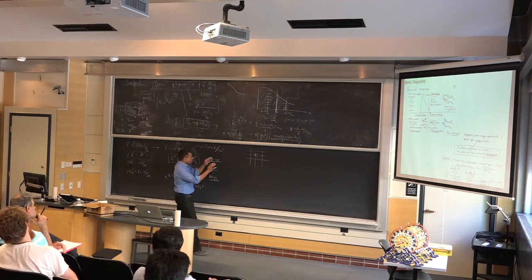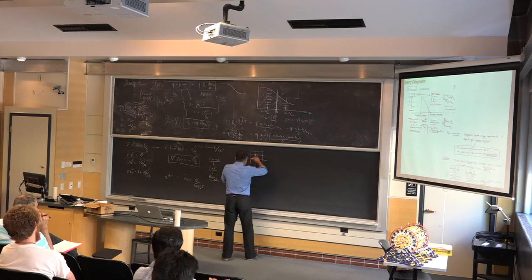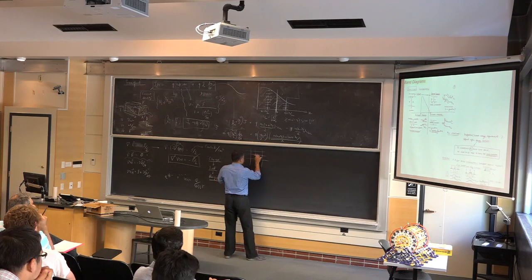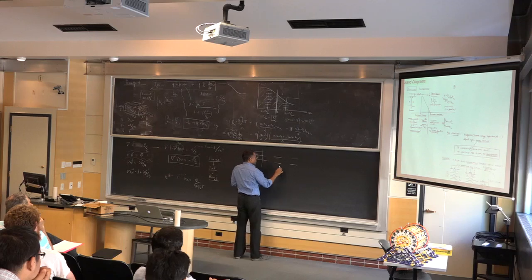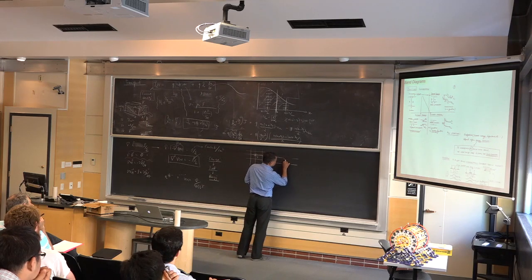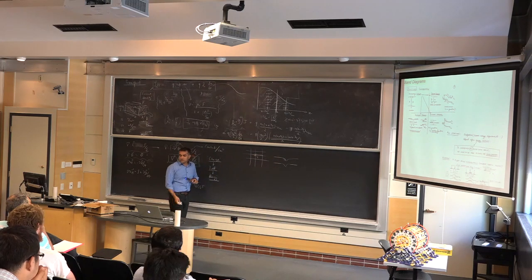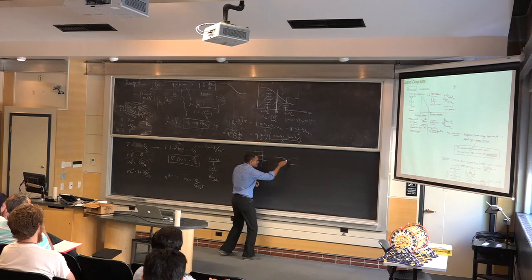If you want to draw the energy band diagram around here, going along that direction, because of the positive charge, microscopically, far away the bands are flat, but very near there's a little positive charge, and you won't go wrong in understanding that the bands will do a little bit of a dip like that, because it's going to pull electrons in. And the nature of that is 1 over r.